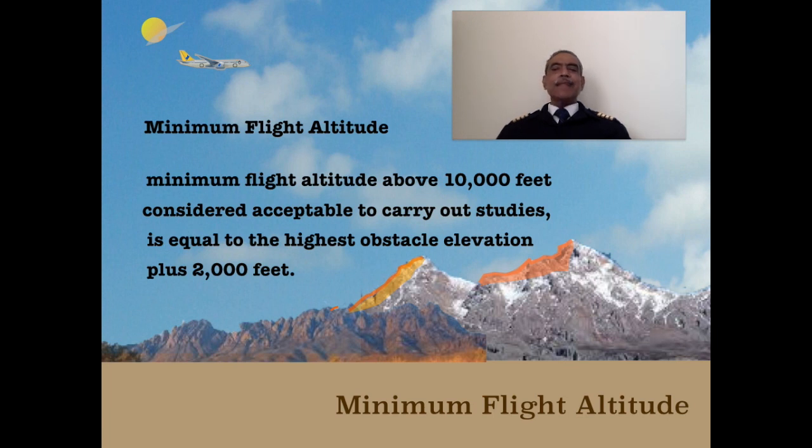It is considered acceptable to carry out obstacle studies and fix up a minimum flight altitude which is equal to the highest obstacle elevation plus 2000 feet. So this is considered as acceptable by almost all legal authorities when planning the en route segment.